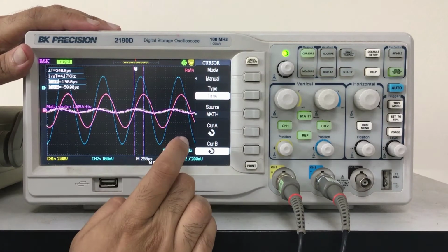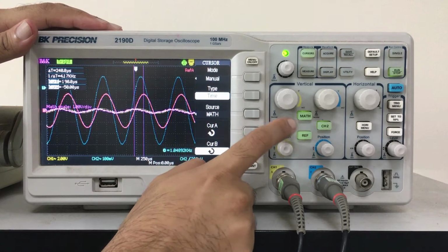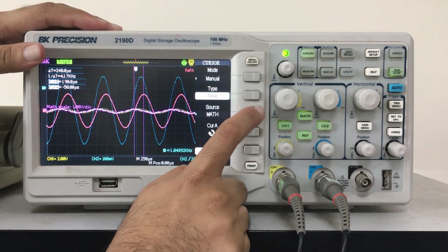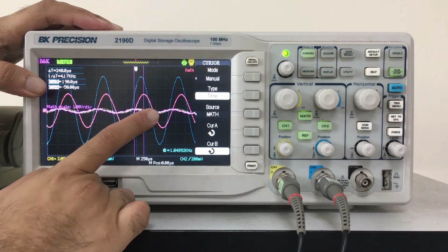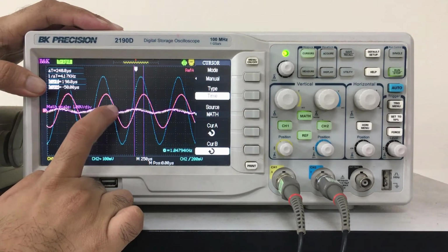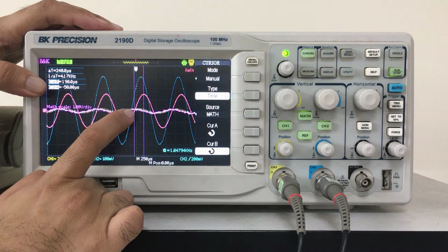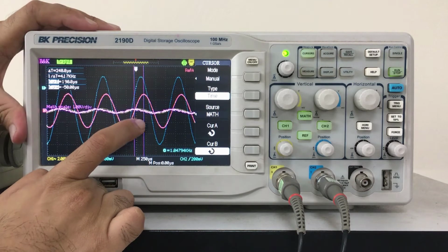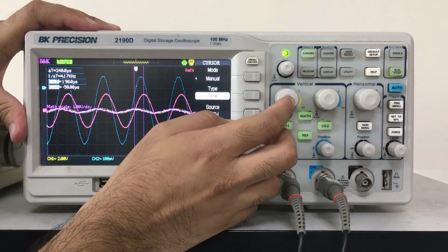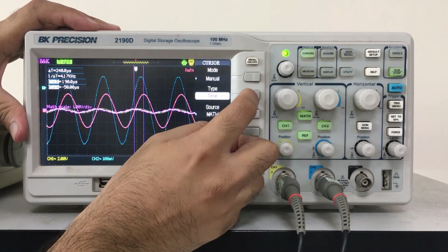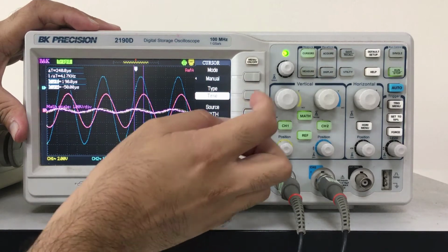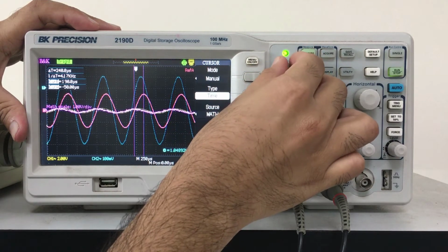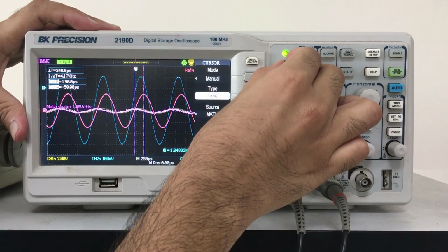After shifting channel 1 to node D, we perform math. Channel 1 minus channel 2, which is D minus B. So this purple signal is our voltage across the sense resistor for the capacitor, RSC. So in this configuration, using cursor, we can measure the voltage and phase of this signal. So if we measure the phase first,